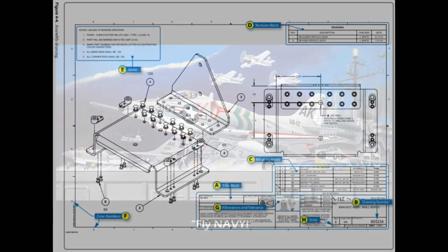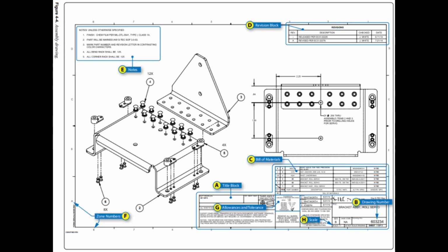Bill of Material. A list of the materials and parts necessary for the fabrication or assembly of a component or system is often included on the drawing. The list is usually in ruled columns that provide the part number, name of the part, material the part is to be constructed of, the quantity required, and the source of the part or material.